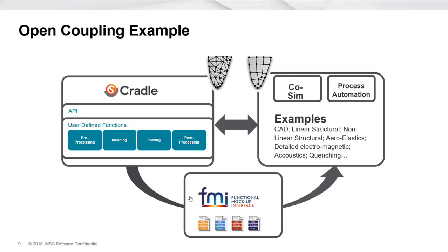What's more, we can also do this through standards. The Functional Mock-up Interface is a great example of such a standard. Here we can start sharing performance results and co-simulating to some extent with FMI with any other toolset that is also based on those standardized protocols that FMI has. So this way we can link together different tools in different ways, in the way we need to.